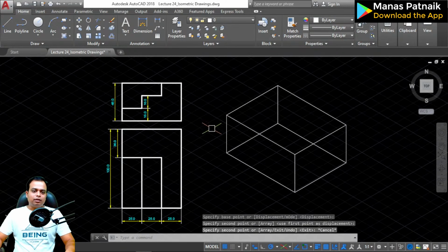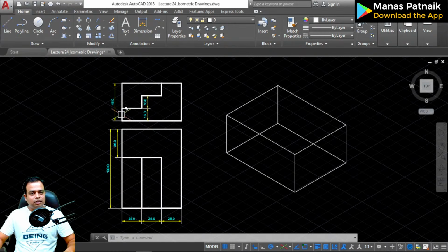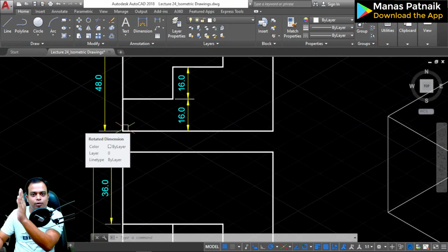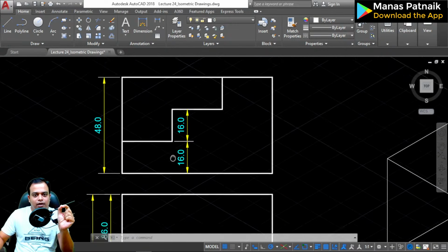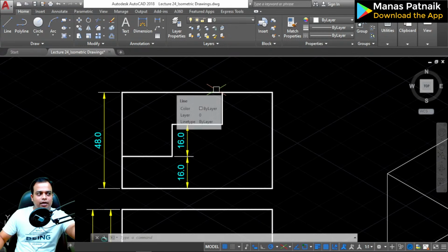Lovely. Now sir, in the front view, this is the front view basically, and that's the top view. Once this isometric view is complete, you'll get to understand how the front views and top views have worked out. You see there is a step, sir. So we need to first of all travel upwards 16, and this way 25. Again 16 and 25, 16 and 25.